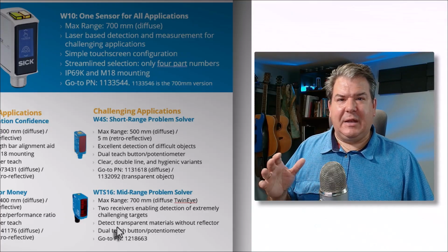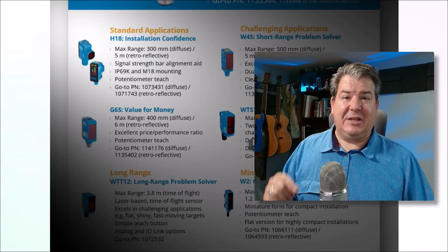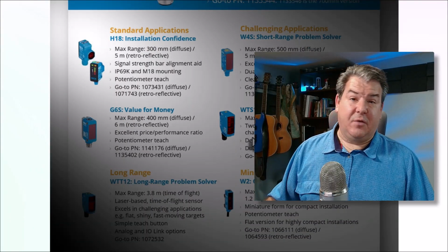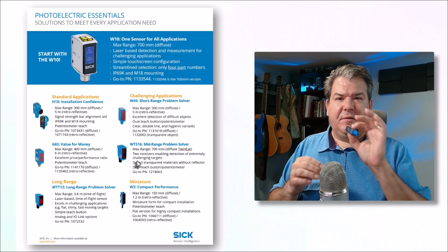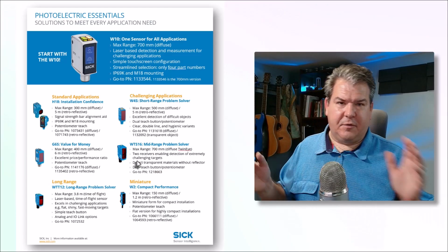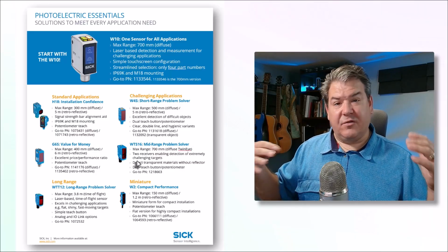But if you simply need a through beam or retroreflective beam break sensor, then something in the H18 family is the way to go, in a retroreflective version and a proximity version. So there'll be some additional sensor information I'll put in the descriptions as well, and key part numbers depending on what you're looking for, maybe the longer range or something.